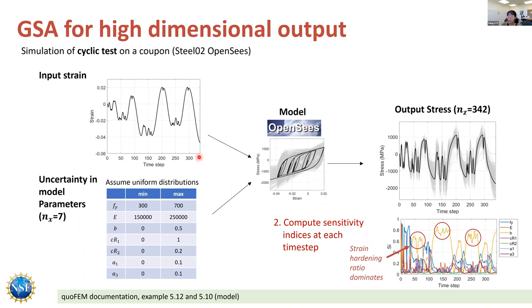And if we inspect the strain curve, that is the time period where we are imposing compression force on our element. So it tells you that when a material is getting compression load, some of the parameters will really affect the response, while other parameters will not be very influential. So this gives you a nice insight on the problem, and understanding of your models.